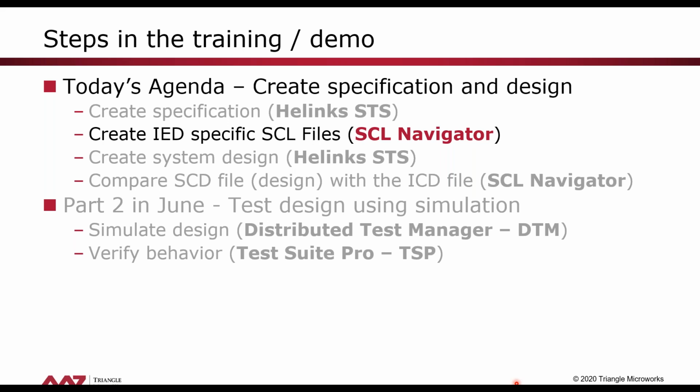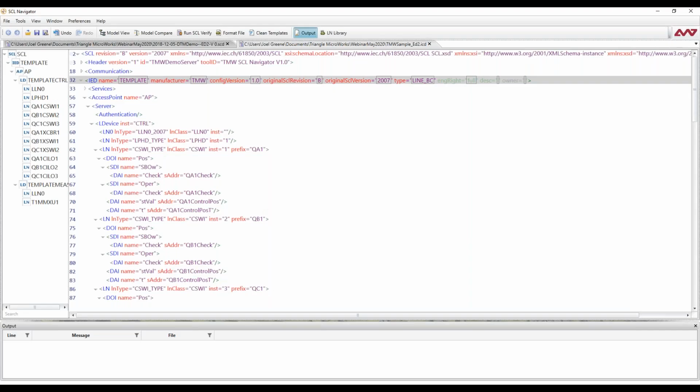So that's the logic, the software that is performing, as an example, an interlocking check to figure out if it's allowed to operate a breaker, that is probably performing synchro check, if we need a synchro check. So that's really the software function that is executing the control. The XCBR is purely representing the interface signals.